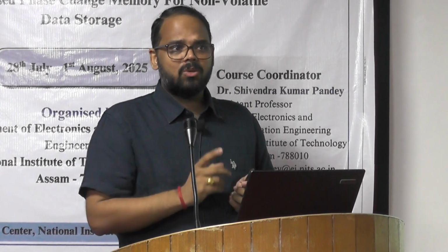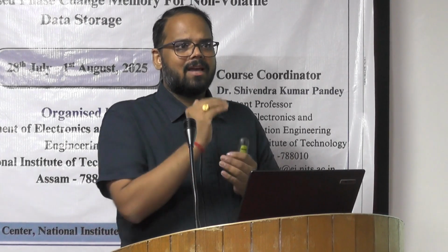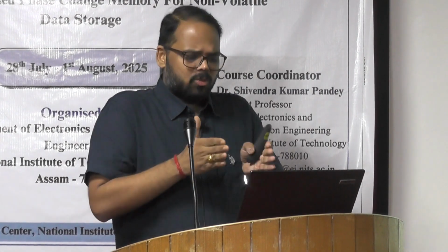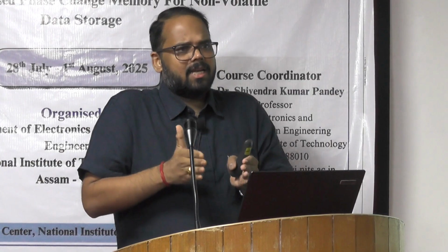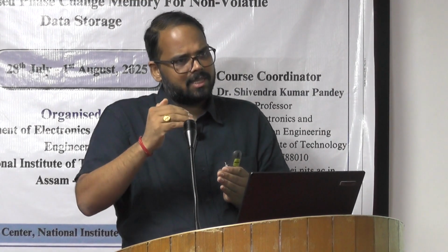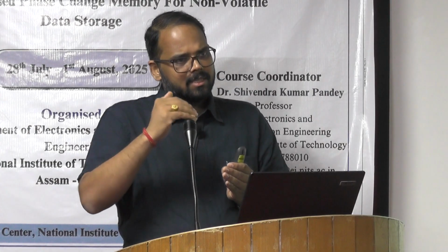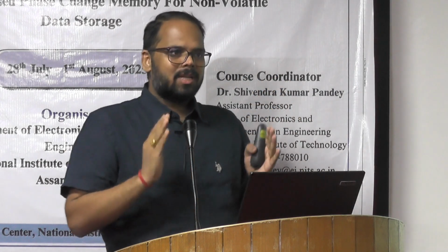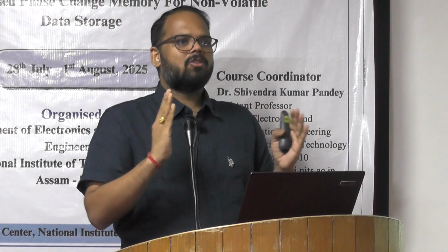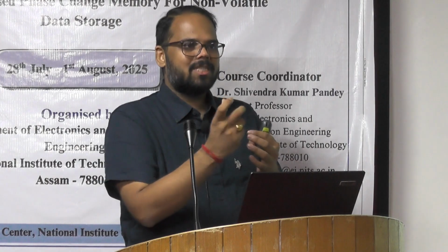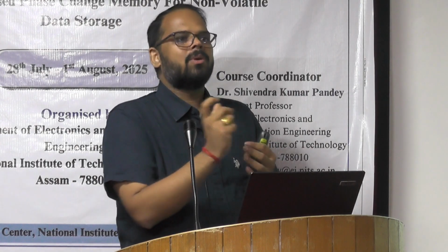For set operation, I told you, you should provide an electrical pulse of lower amplitude but longer duration. You fix one pulse and systematically provide those pulses, increasing the amplitude, and you can see the change as an increase in conductance. In that work, the pulse duration is on the higher side. Why? Because we need to set our device. So it's potentiation. Potentiation means you are just tuning.